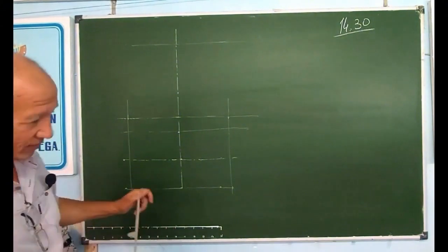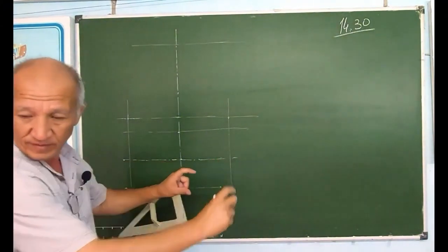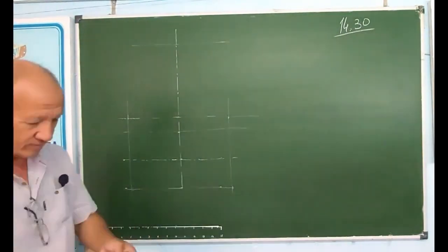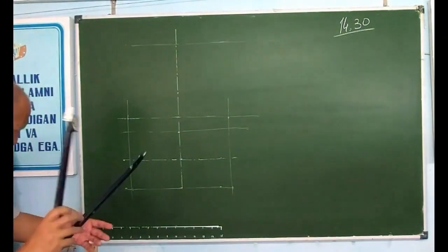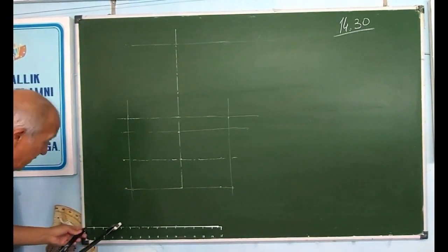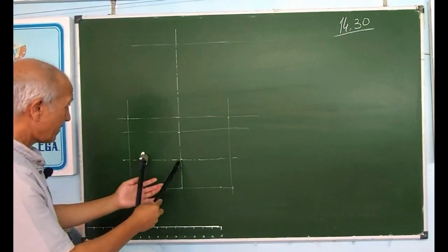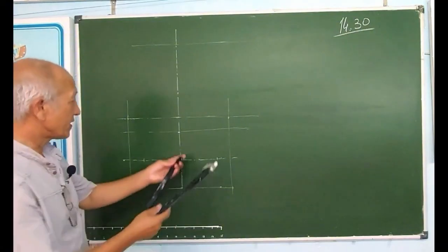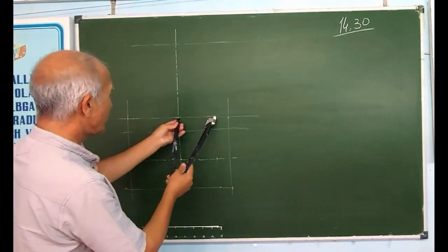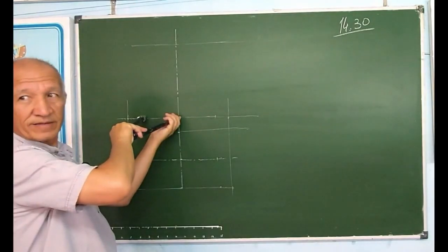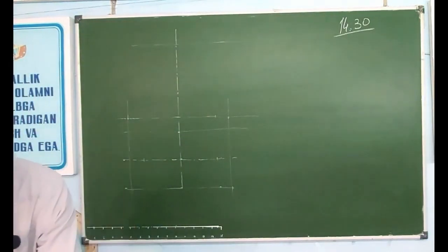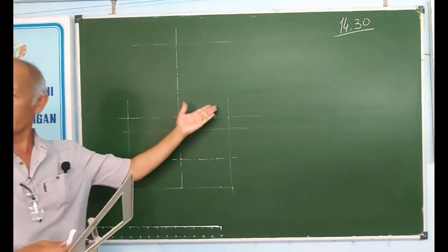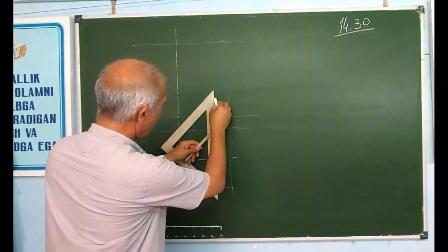There's a part that goes inside. Both of these parts go in here, right? So how deep is the part that goes in? How much? That's it. If you take it to 40 and place it like this on both sides, is that enough? Of course, is it necessary to subtract 110 and do it differently? Is it not necessary? It works just fine this way. Okay, now look, I'm drawing on this side. It's not necessary to draw on this side. Actually, you've already drawn it here, if you draw it correctly. Do you know why? Because after we've made the cut here, we don't show this side. We show the cut on this side and draw it all in one go, like this.